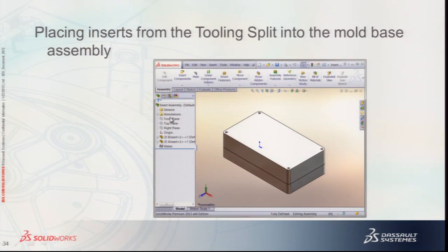And as a result, I have an assembly file with my insert in my solid body geometry. You can use this any time you have a multi-body part. You can easily convert it to an assembly and have individual part files. And once again, this is linked back to your original model, and design changes should propagate back down to this.